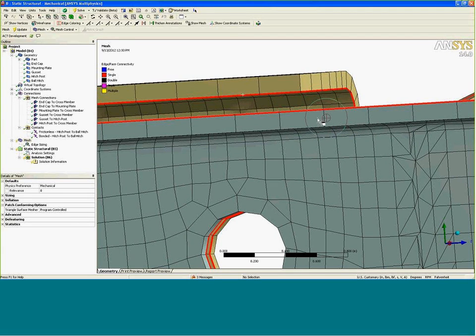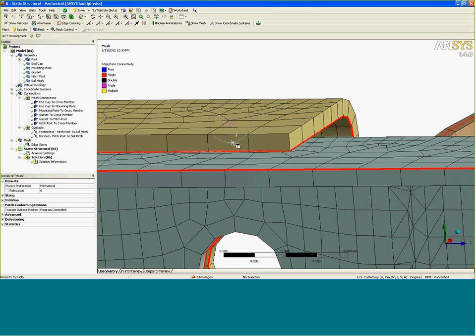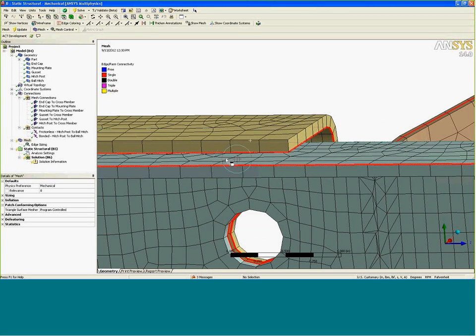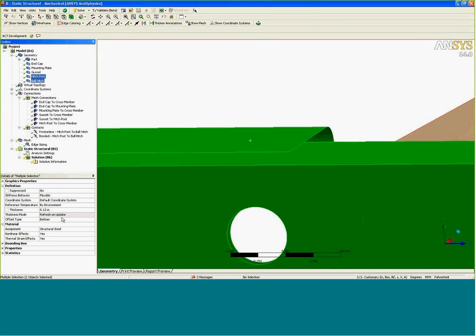It used to be at the middle for the midplane. So the middle of the shell section was aligned with the surface body right here. So now set it to the bottom. So the bottom of the shell section is aligned with the surface body. So that's clearly the bottom. And on this side, that's clearly the bottom. So easy to check that too. Or if you wanted to include some offsets in the sections, that's how you could do it. Set these back to middle in here.